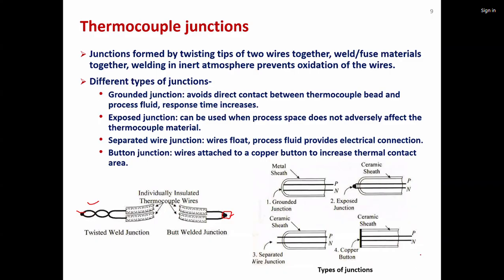But the good thing is that there are some corrosive fluids which will degrade the wires. For long-term use, you have a metal sheath which is resistant to the process fluid. You compromise in terms of the dynamic temperature measurement, but that is something that your system requires. So you can make a connection through a metal sheath.